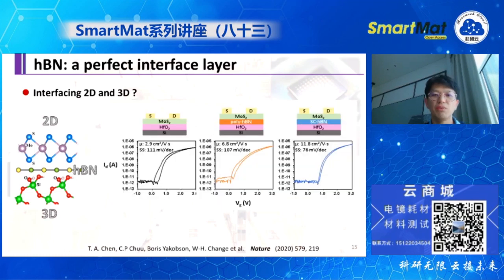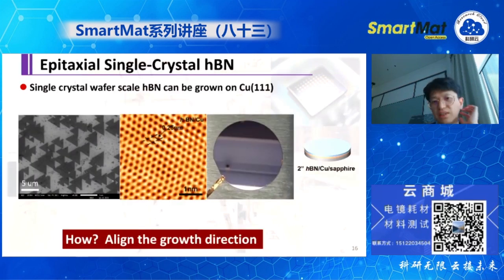Okay. So I won't discuss too much the benefits of hexagonal boron nitride, but the thing I'd like to discuss is that recently we found a way to control the hexagonal boron nitride orientation. Hexagonal boron nitride is the same as MoS2. When it grows, if you have hexagonal boron nitride triangles pointing in opposite directions, like 0 degree and 180 degree, when they merge they form a grain boundary, which is not wanted.